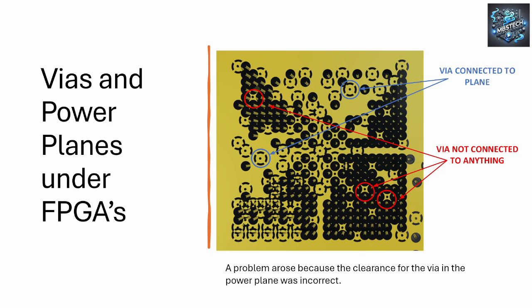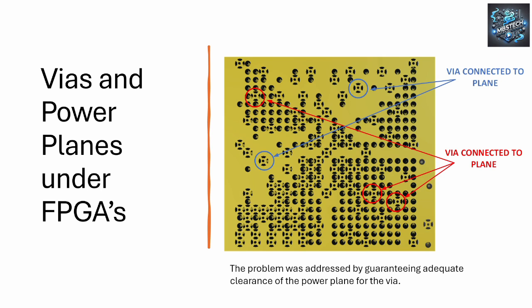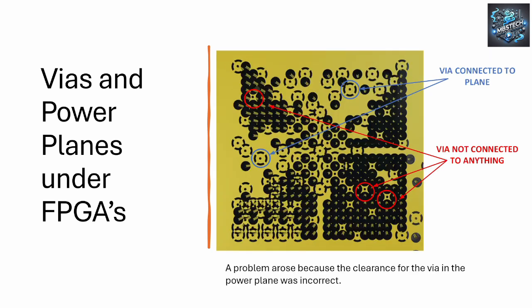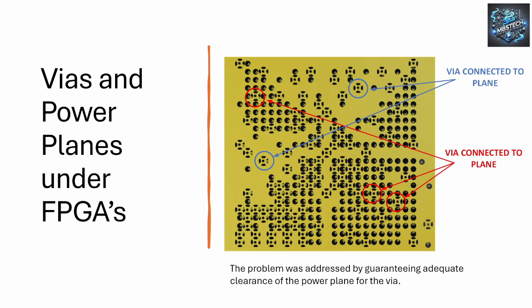Okay. How do we do this? Well, this is what you do. You alter your power plane clearance rules, and now those same wires that we saw in the previous slide, there you go, same wires are now connected to a solid ground plane. Okay, you've still got perfectly good clearances, everything's good, right? So you need to address power plane clearance rules. They not only affect your chip from a thermal point of view, but they just create impedances in your planes, which is not good.